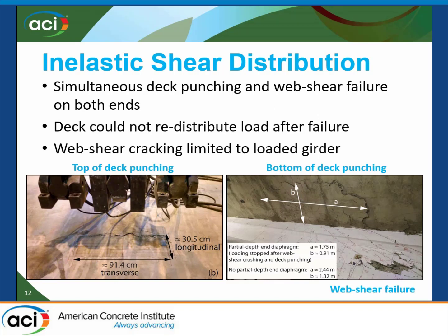The way it worked is that below, I removed the frame you're talking about, the steel beam below the picture here. The steel beam came down to a neoprene patch, which was pretty much that size. You can see the arrows on the left picture, 91 centimeters and 30 centimeters. And we just physically couldn't apply the load in a smaller area. So it definitely influenced the punching in that that's the surface it punched. Had it been over the deck, as the first question suggested, we probably would have punched straight through the deck and not applied the load on the girder. So we kind of did the best we can. An ideal scenario would have been to apply this magnitude load with several actuators spaced like an axle or axles, but that's even harder.